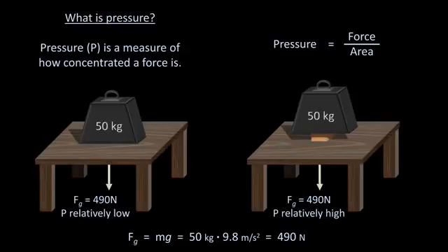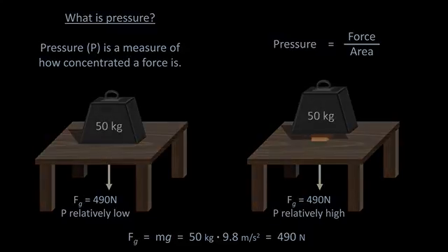In fluid mechanics, instead of one solid object imparting pressure against another solid object, we have a fluid imparting pressure against a solid. But the concept of a force per unit area is the same. When talking about fluids, there are a number of different types of pressure that one can discuss. The most fundamental and important of these is something called the hydrostatic pressure. This is the pressure present within the fluid when it's at rest.